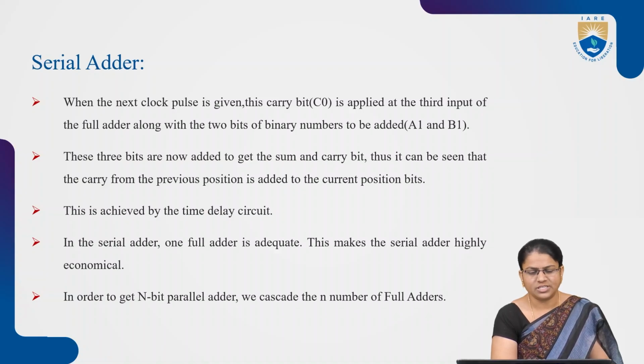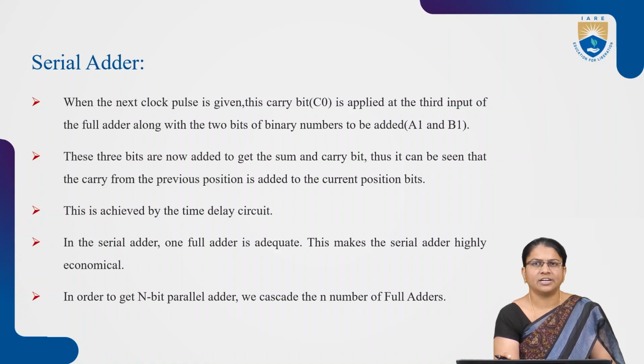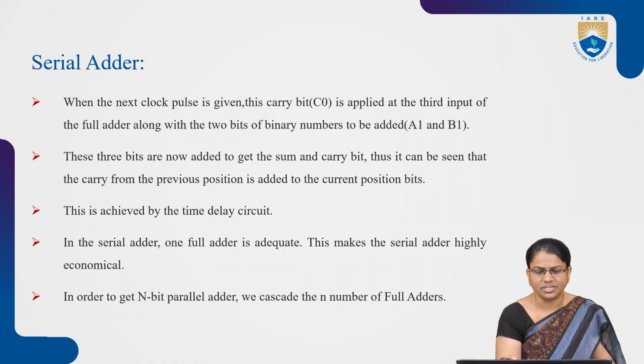And in case of a serial adder, one full adder is adequate. Means serial adder is highly economical. Why? Because the bits are transmitted bit by bit, so it will take a long time to deliver the output. Because of the delay, the outputs are calculated very slowly. That is the main drawback of a serial adder circuit.